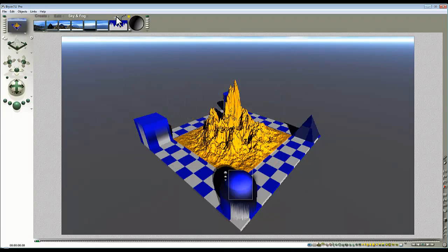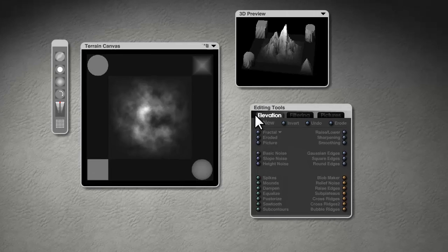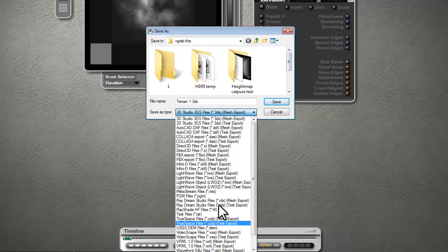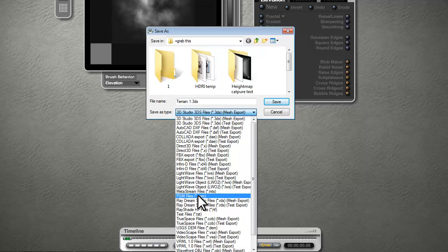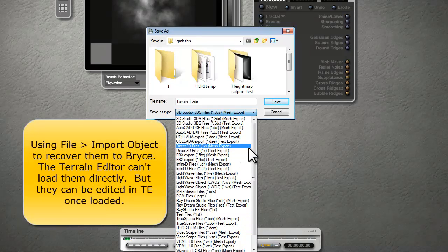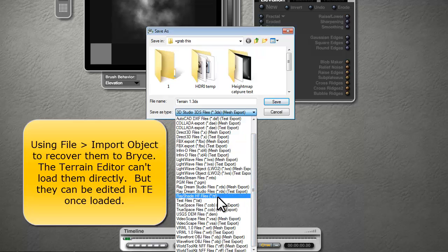As far as exporting is concerned, this is something I was looking at, no, not in there, in the terrain lab. None of the export options here for export image allow it to export an image at, or at least reliably, any 16-bit resolution. I get the impression it occasionally does it, but it doesn't seem reliable. It seems to export always at 8-bit resolution. Of these export formats here, as meshes, the OBJ format works very well, but obviously you've converted it to a mesh. PGM files and DEM files worked fine. This HF file format didn't produce any sensible output.